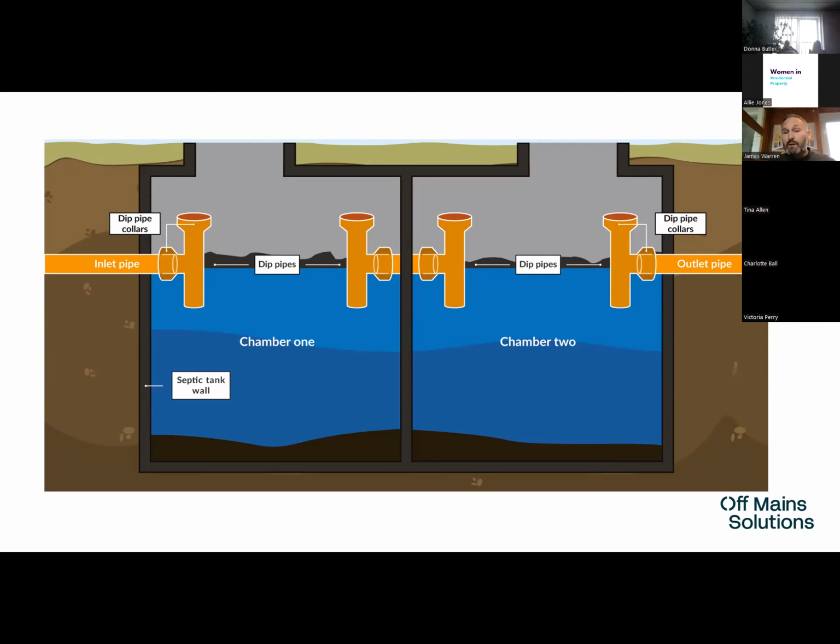So in this illustration we're looking at now, we're looking at a septic tank at its natural operating level, which means that the liquid is at the height of the inlet and outlet pipes. That's how the waste and water comes in and how it eventually is allowed to exit the septic tank. Now with displacement, all it means is if 500 litres come into the septic tank, 500 litres need to exit. And if the separation process hasn't occurred in that time, then it's going to push through matter that should always be retained inside the septic tank.